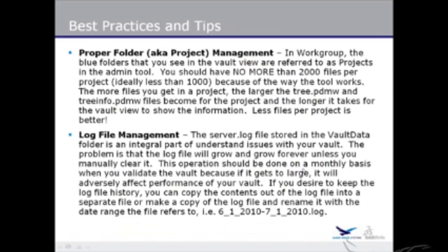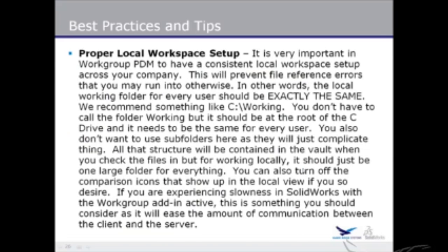Okay, so one of the next things is the proper local workspace setup. So we talked about this. This is a big deal, okay? Everyone in your company should be using the exact same working directory. If you have C Bob desktop working and C John desktop working and C Susan desktop working, you're going to have issues with file references.